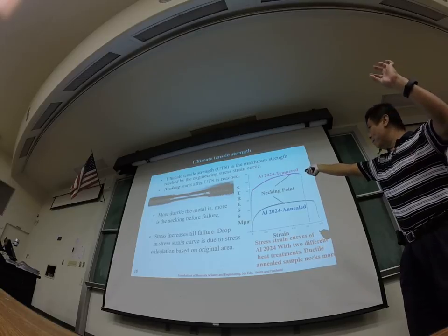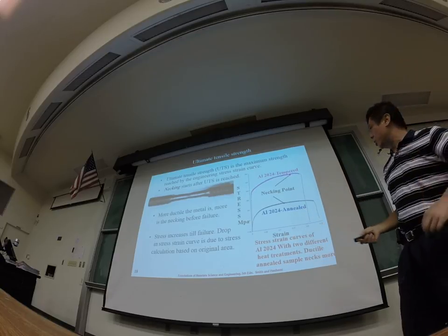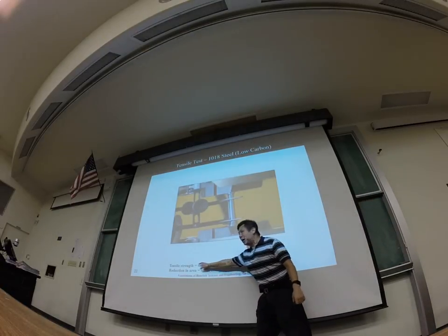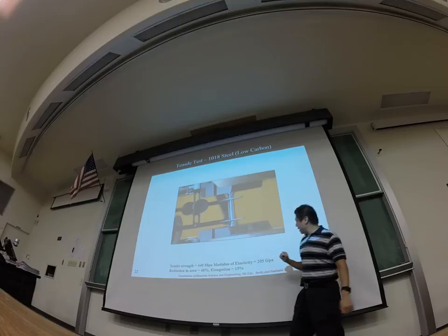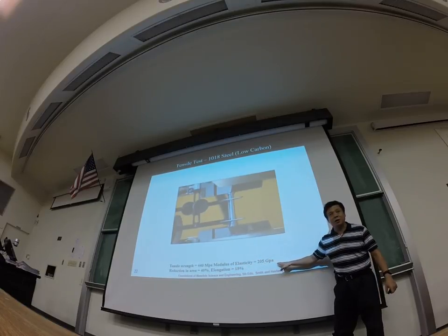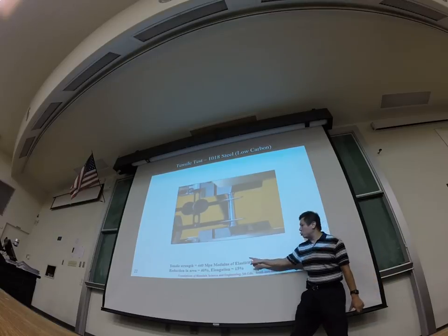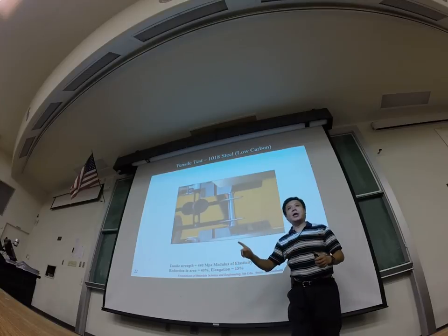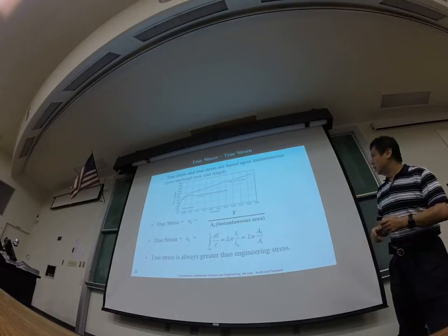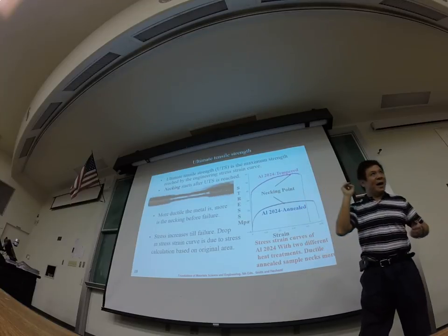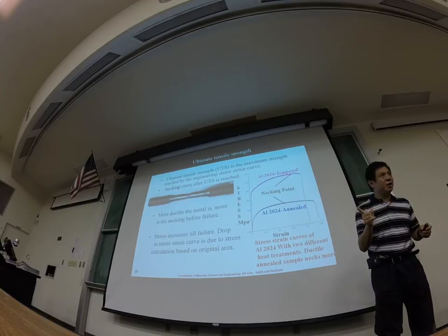At the maximum point of this linear range, by measuring this sample, you got 440 megapascal, and the modulus of elasticity is 205 gigapascal. Based on these two values, can you tell me what is the maximum strain at the end of the elastic stage? Can you calculate that?